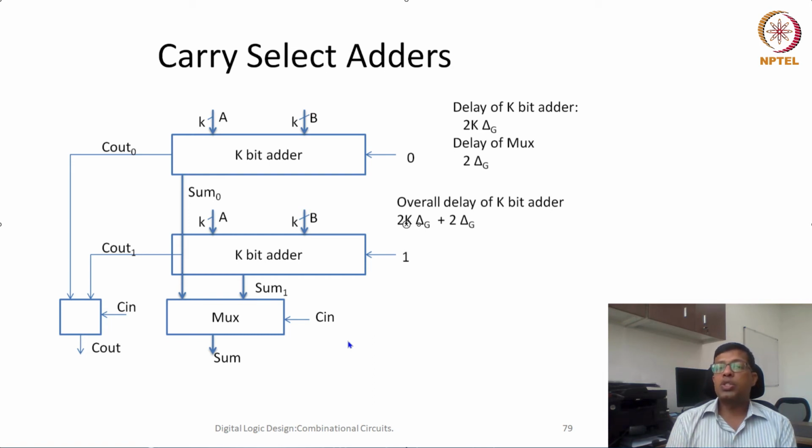So this is also called speculation in some cases. Speculation means that we speculatively assume that if the output is going to be 0, then we can do this, and if the output is going to be 1, then we can do this particular processing, and then when we come to know what the output is, based on that we can select our final output.